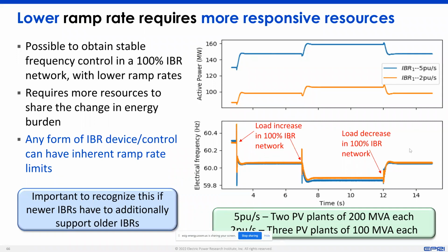So what we have done essentially there is then not saying that when the inverter is responding, it will hit the absolute current limit for reactive current, which will make the active current go down. So what it would do is it would hit a lower limit for reactive current, which still allows active current to come through and allow that load to not stall or not fall down, but then help maintain the voltage profile and help support the voltage while also feeding active current.